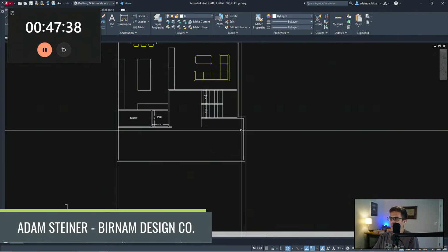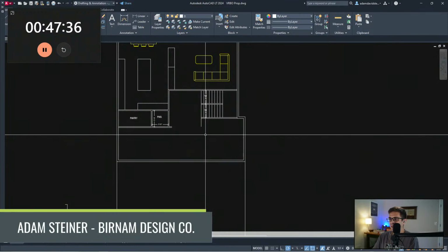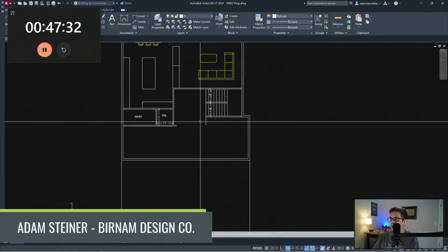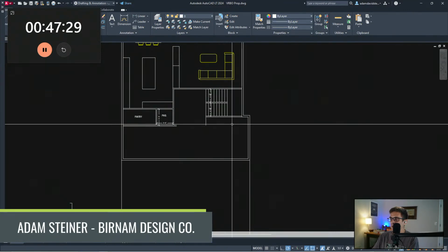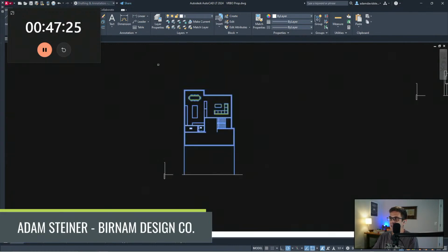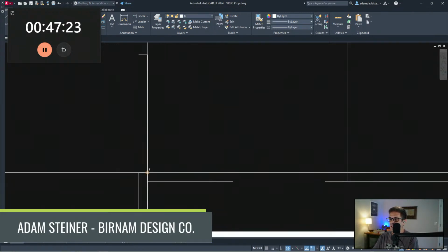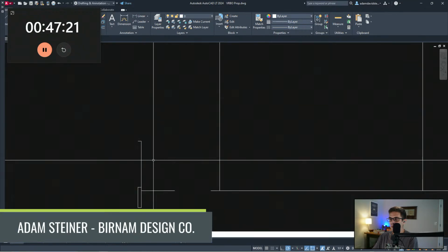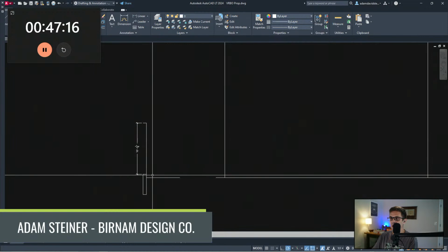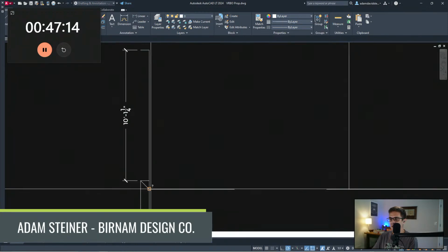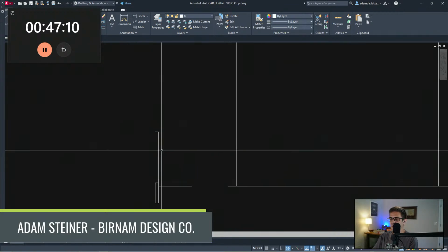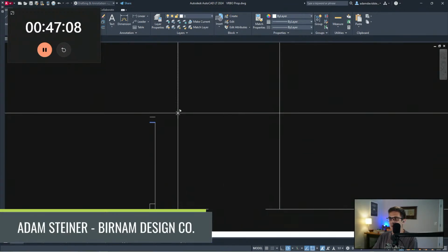And then this is enough room for a bedroom. Maybe not a super luxurious bath. So kind of thinking like do the stairs move so you can do a private bath back here or something. We're going to play with that, but not quite yet. First, I want to get to the elevation. Okay, so I'm showing slab on grade. So grade 8 inches is 8 inches below top of foundation. That's 10 foot 1 1/8. That is rounded to every 1/4 inch. So I didn't look right.